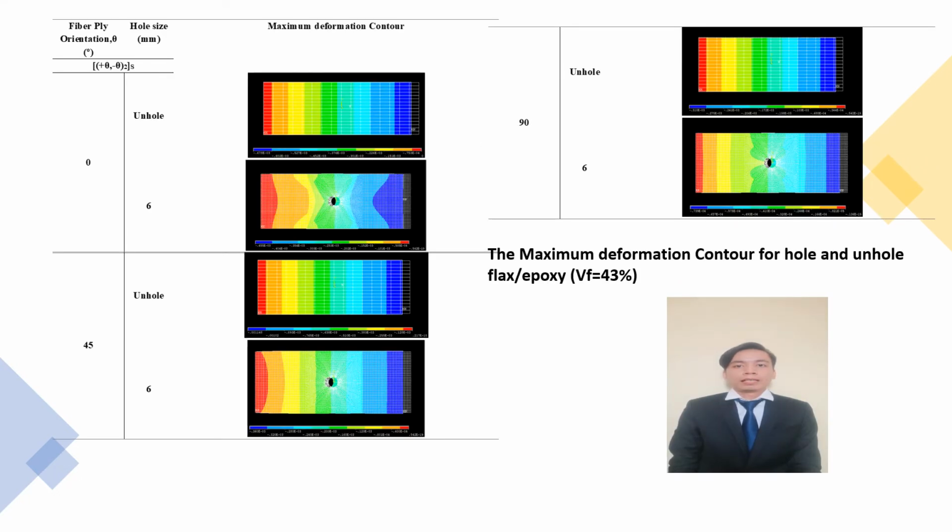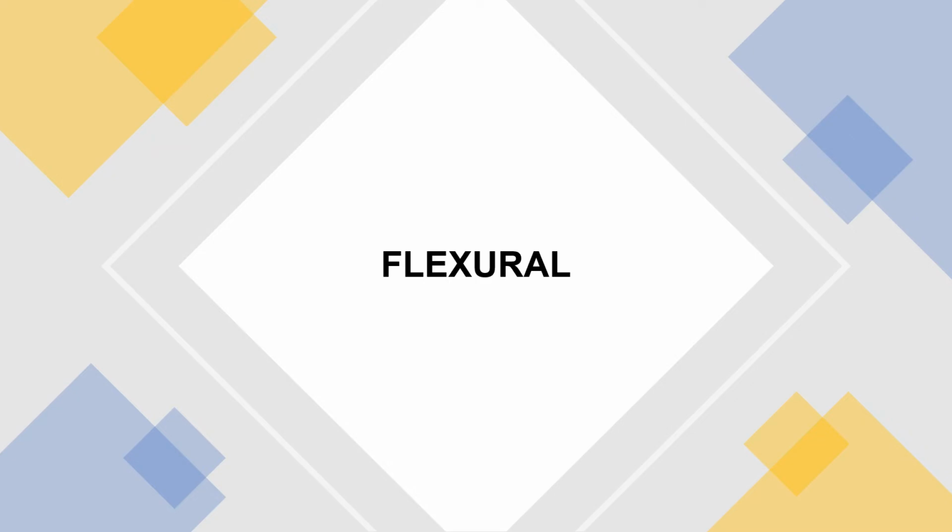This table shows an example of the maximum deformation contour for hole and unhole flax epoxy that was done in Ansys software. This table shows the maximum deformation is also influenced by the composite maximum stress. If the maximum composite stress is highest, the maximum deformation is also highest.